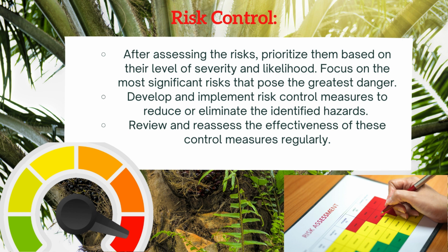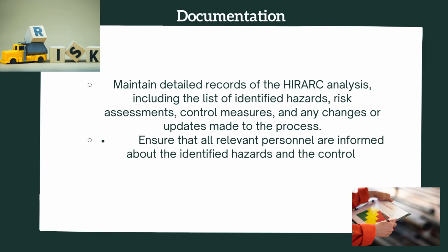4. Documentation. Maintain detailed records of the HIRARC analysis, including the list of identified hazards, risk assessments, control measures, and any changes or updates made to the process. Ensure that all relevant personnel are informed about the identified hazards and the control measures in place.